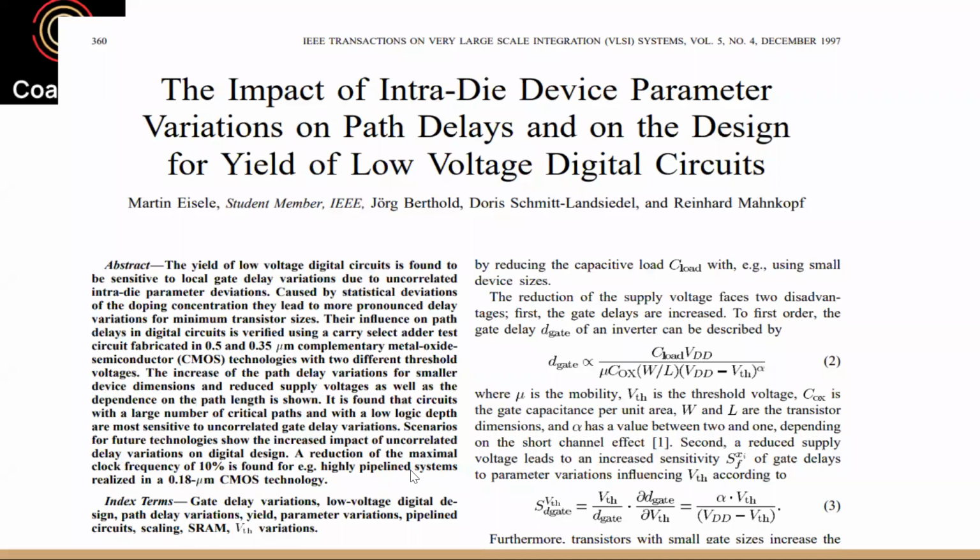usually in textbooks, or in older technology notes, very old, like almost 25, 30 years back, even let's say 15 years back, PMOS was wider because hole mobility is around half of the electron mobility. Therefore, if you want to have the same resistance for PMOS and NMOS, you have to widen the PMOS 2 times than the NMOS.